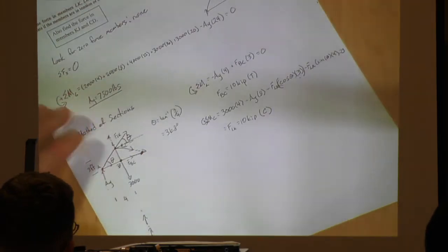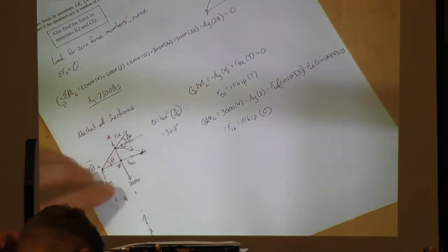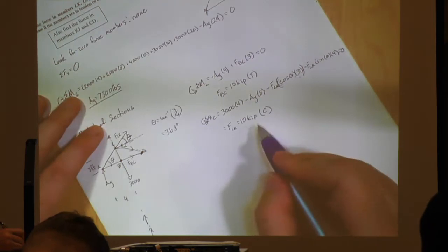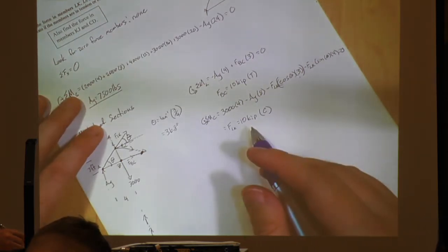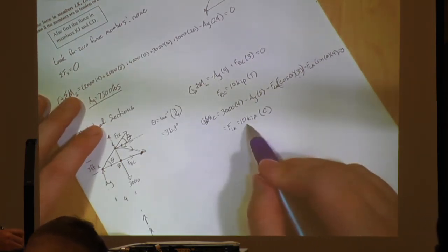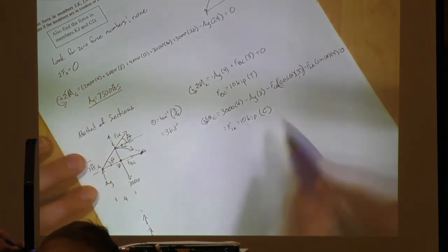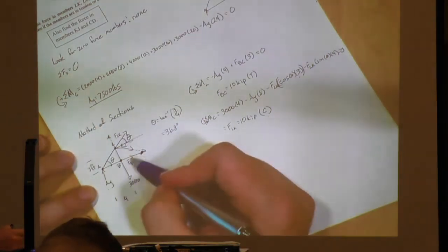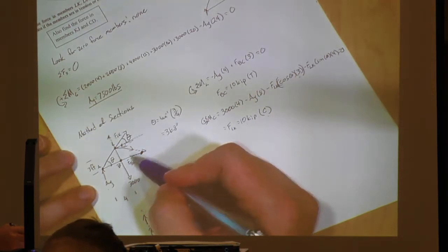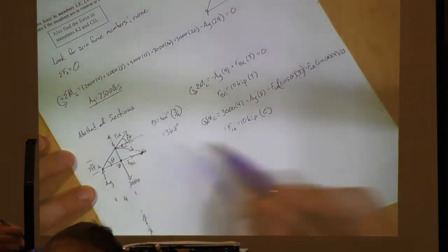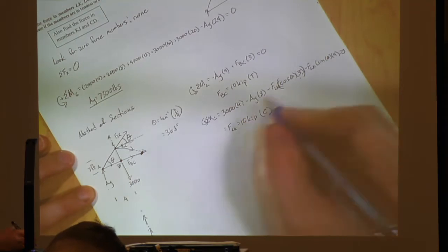So it's in compression. So actually, when you do it, it becomes negative. Yeah. So either you can leave this as a positive and put C, and then go back over here and update your arrow, or leave your arrows the same and leave this as a negative and label it still compression.